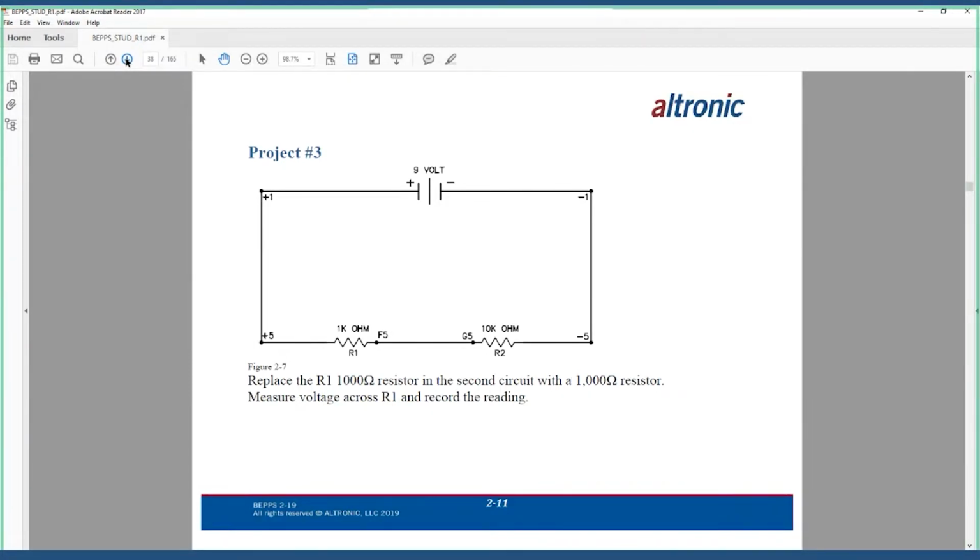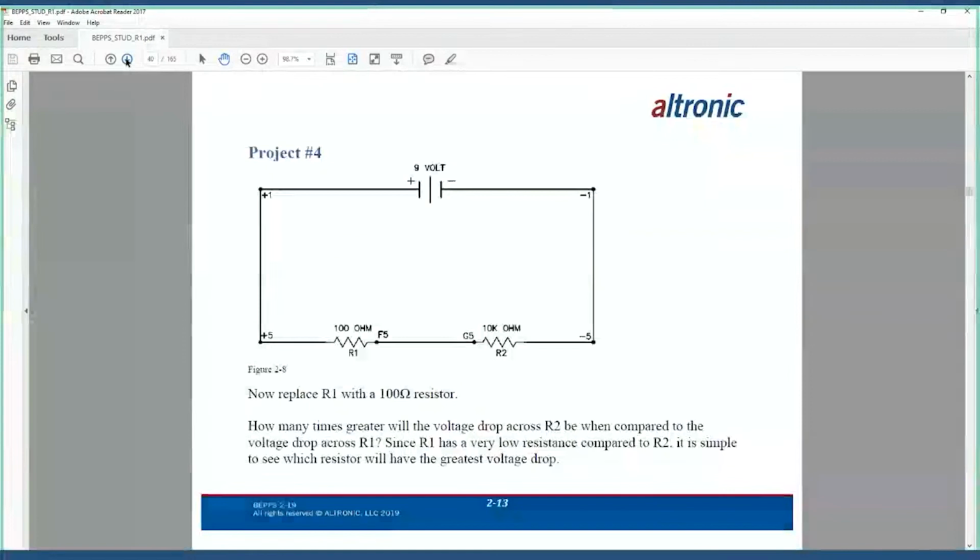We went back and reworked it, found a mistake that we made, and we added everything back up, and we were just under 9 volts, which is where we should have been if I had not rounded off my very first calculation on figuring out what the amp draw was on the total circuit. We would have come out with a perfect 9 volts again. And that's kind of proof in the pudding that Ohm's law does work. Any questions?